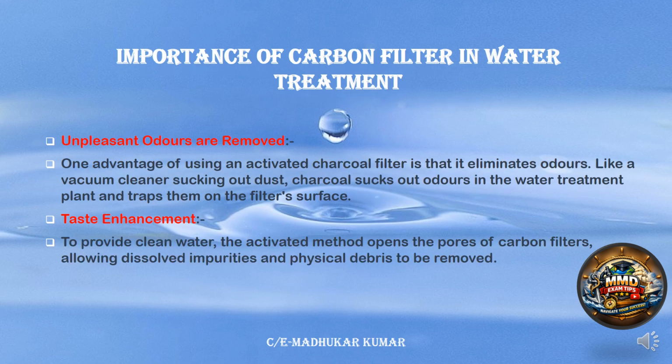Unpleasant odor. Yes, it sucks the odor. Like we have the vacuum cleaner that sucks the dust, it absorbs the odor, and the water has a good taste. The odor is also removed, and taste enhancement is also there. The activated carbon is there. The water passes through the pores of the carbon filters, and dissolved impurities are also removed. Physical debris is also removed, and it adds some taste also. So any water passing through the activated carbon filter will have the odor removed and the taste enhanced. That's why we utilize the activated carbon filter for the post treatment of the water.